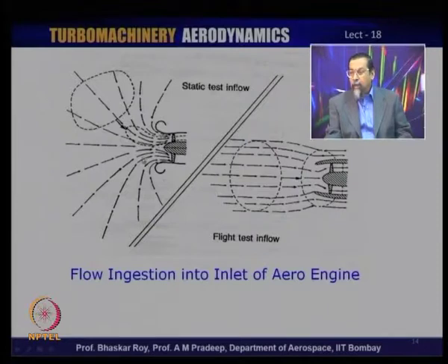So, the inflow characteristics during the static test or during takeoff are quite different from when the aircraft is flying, when the air is going into the engine in a more uniform manner. So, the manner by which the air is ingested into the engine also in a way decides how the noise comes out of the engine and is propagated.